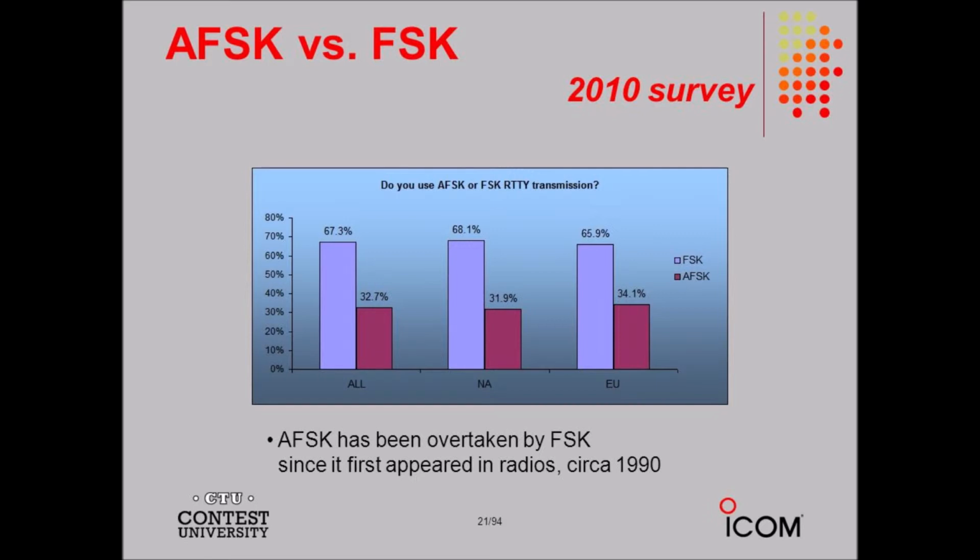The maximum reference amplitude equals 0 decibels relative to 1 milliwatt, abbreviated as 0 dBm. The data exists in sidebands above and below the carrier frequency. These sidebands constitute sum and difference signals produced by mixing in the modulator circuit between the audio and the carrier.